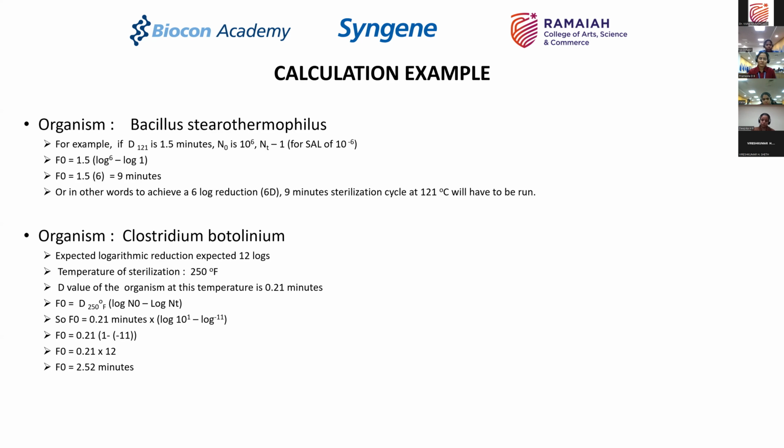You had a load of 10 garments, 20 spatulas, 15 filling nozzles kept in a load. And one cycle you ran it and you had a validated cycle which said you should ideally run this cycle for 20 minutes of sterilization hold time, which here we are talking about the whole time. Okay. So I was supposed to run it for 20 minutes.